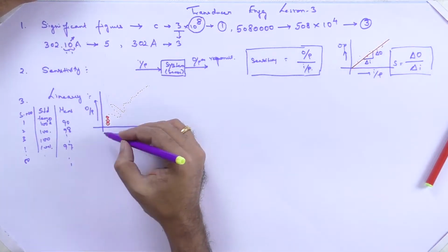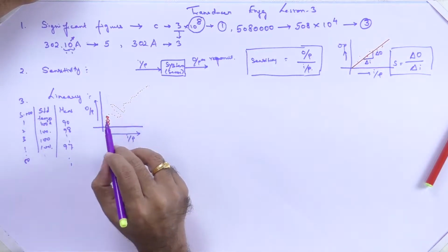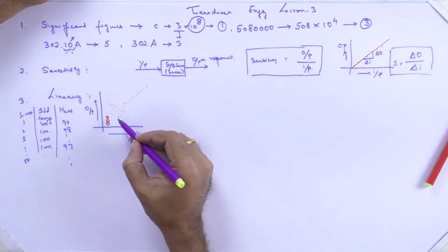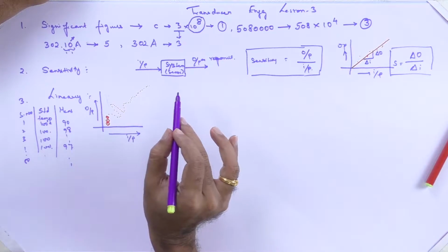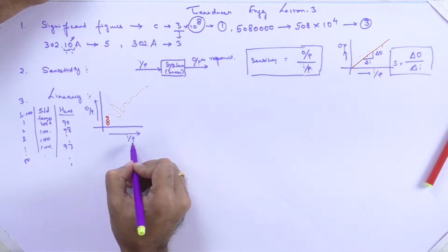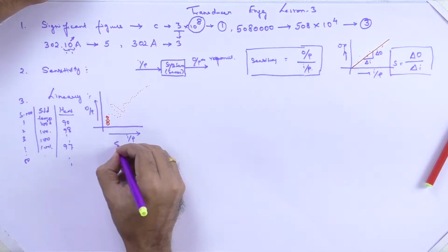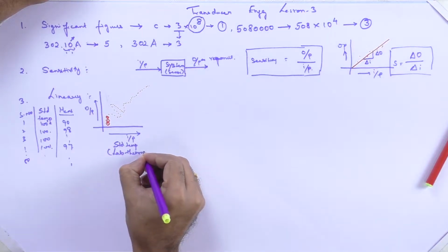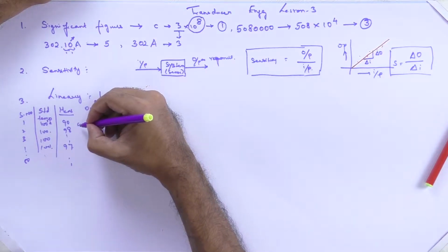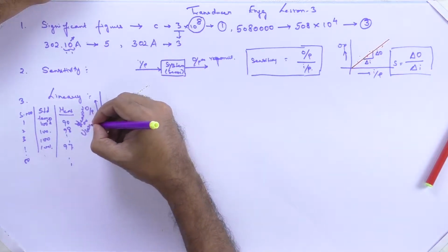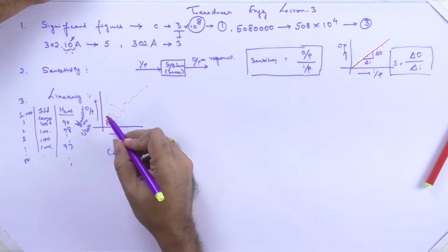Okay, there's no confusion, it's simple. It is an input-to-output graph that is being plotted over here, and that gives a response in this fashion. We can't expect a typical straight line at the initial phase itself from our measured quantity. Here the input quantity is the standard or independent quantity, that is your standard temperature from your laboratory thermometer, and the output comes from your measuring thermometer.